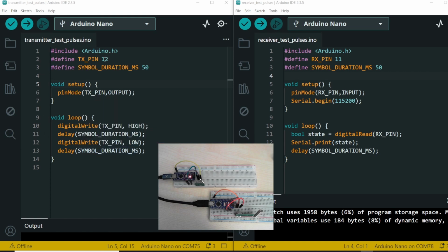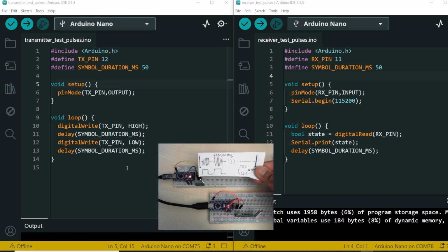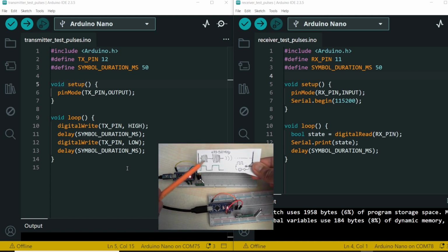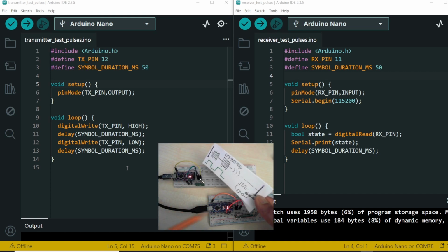To remind you, my output pin is connected on the GPIO identifier 12, the D12 pin. So this piece of program is going to forever try putting out pulses on the transmitter side. So if you remember, if this happens, then on the air we should have the 433.92 megahertz pulsating in this form, and this is going to come onto the receiver board. Good. Then on the receiver side, once again a simple program.